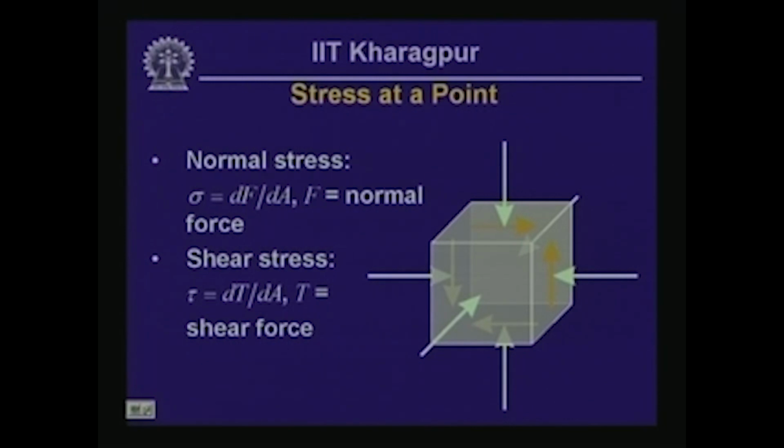shear stress arising on horizontal planes at the top and bottom of the element, acting in clockwise direction in an opposite sense to the shear stresses that were operating on the corresponding vertical planes. So you should notice here that all the four shear stresses will act together in order to maintain equilibrium. All of them have to arise together, or they are not going to arise at all.